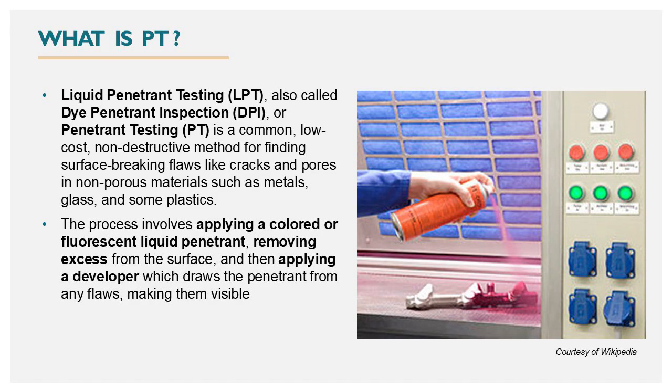What is liquid penetrant examination? Liquid penetrant testing or LPT, also called dye penetrant inspection or DPI, or penetrant testing or PT, is a common, low-cost, non-destructive method for finding surface-breaking flaws like cracks and pores in non-porous materials such as metals, glass, and some plastics. The process involves applying a colored or fluorescent liquid penetrant, removing excess from the surface, and then applying a developer which draws the penetrant from any flaws, making them visible.